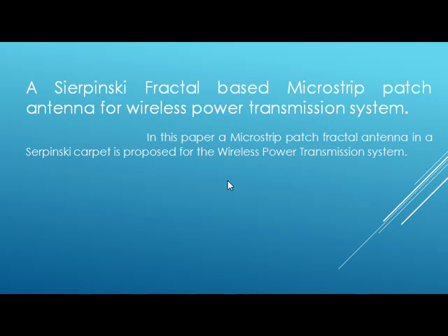Why should it be 2D? I'm sorry, antennas aren't 2D, right? The Yagi antenna has a director, a reflector, and a radiator, the driven element. There are 3 elements in the Yagi antenna. It's a 3D element. You've got several focusing elements, perhaps, but you've got the driven element, then there's a reflector, and then there's a director. And you could have multiple directors, and you could steer it around, and it gives you focusing. A Sierpinski carpet, by its very nature, is 2D. But if you use a Sierpinski sponge, then you have a 3D fractal antenna.